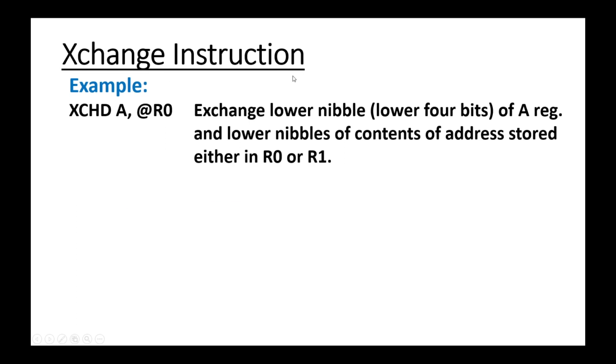The last variation of the exchange instruction is XCHD A, @R0. R0 is a pointer register. It exchanges the lower 4 bits of the accumulator register and the lower nibble of the contents of the address stored in either R0 or R1. Here we have to consider R0.